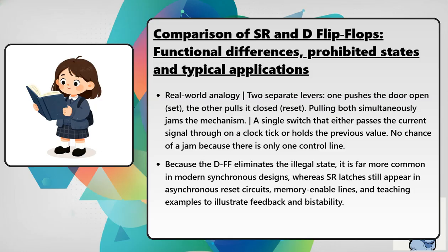Because the D flip-flop eliminates the illegal state, it is far more common in modern synchronous designs. Whereas SR latches still appear in asynchronous reset circuits, memory-enable lines, and teaching examples to illustrate feedback and bistability.